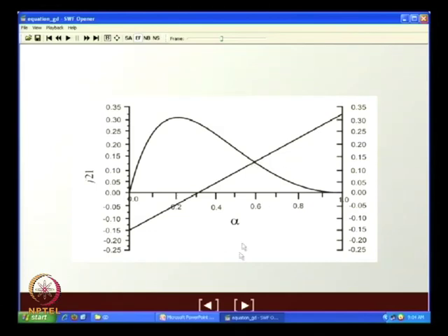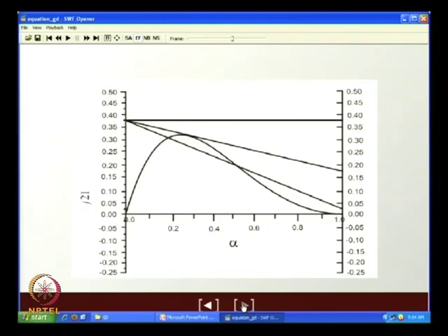Clear? Achha. Then next we found out that for countercurrent operation, gas up, liquid down, either two solutions are possible. Under one particular situation, only one solution is possible. Beyond that, no solution is possible. In other words, countercurrent operation with gas up, liquid down can occur only under a set of conditions. Beyond the flooding point, it is not possible.